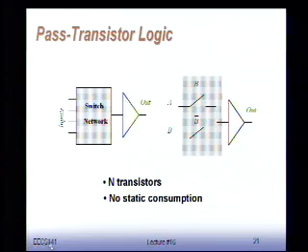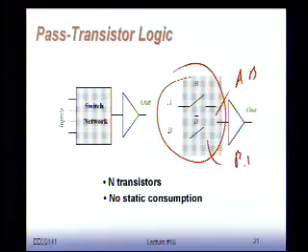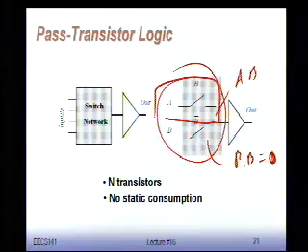So I can do any logic function by putting switches in sequence, like we would do with relays, mechanical switches, and so on and so forth. Same deal. For instance, I claim that if I have 2 switches here, one of them is A controlled by B, so this implements the function AB. And this is B controlled by B bar, which implements the function B B bar, which is equal to 0, sorry.